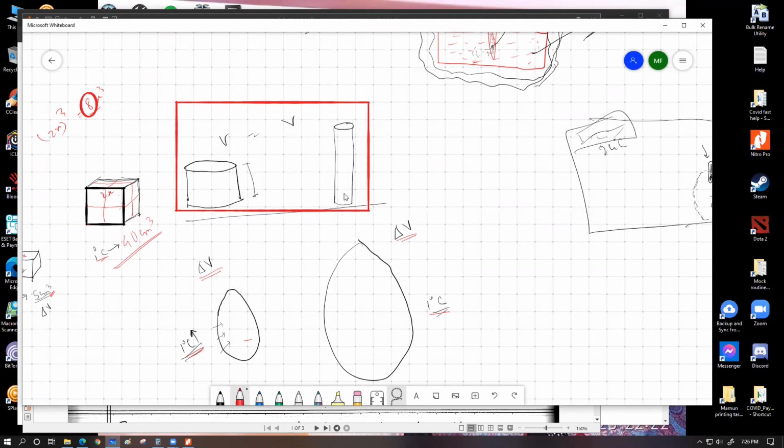And of course, because both the thermometers are considered to be of exactly equal lengths, this one will reach the top of the bore earlier, and this one will take a much higher temperature to reach the top of the bore, which means effectively this one will have a much smaller range. This thermometer will fill up its length for a smaller temperature compared to the maximum temperature measurable by this one. So this one has a high sensitivity and less range. This one on the other hand has a smaller sensitivity but higher range.